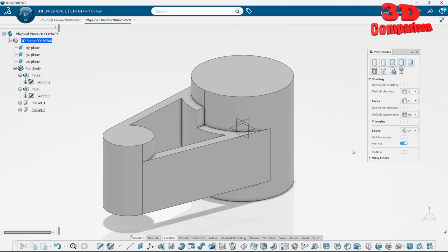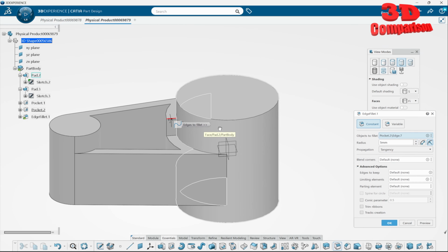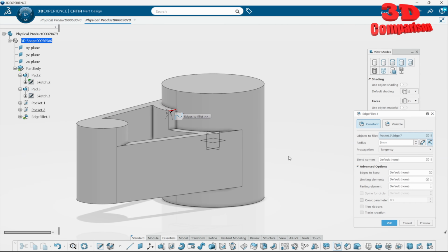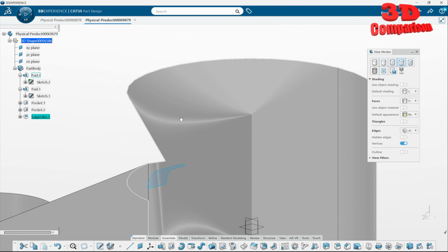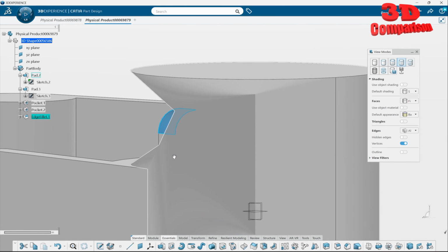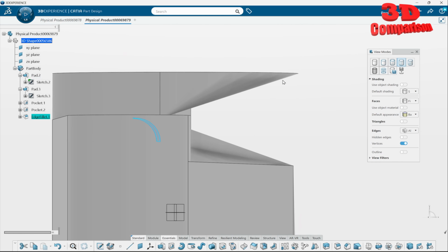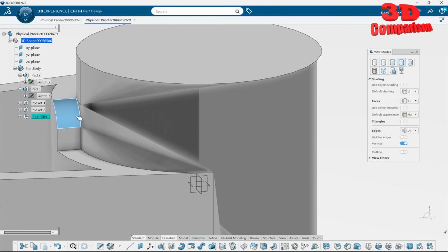And if I try to use the fillet, something really odd will happen. So if I just edge fillet the top one, if I hit preview, now if I rotate, we're going to see that this cylinder still has the material normals. But if I hit preview and OK, we see what happens over here. So even though this is part design, not surface design, it will act like this. So we have an inner fill over here that tries to apply that fillet.